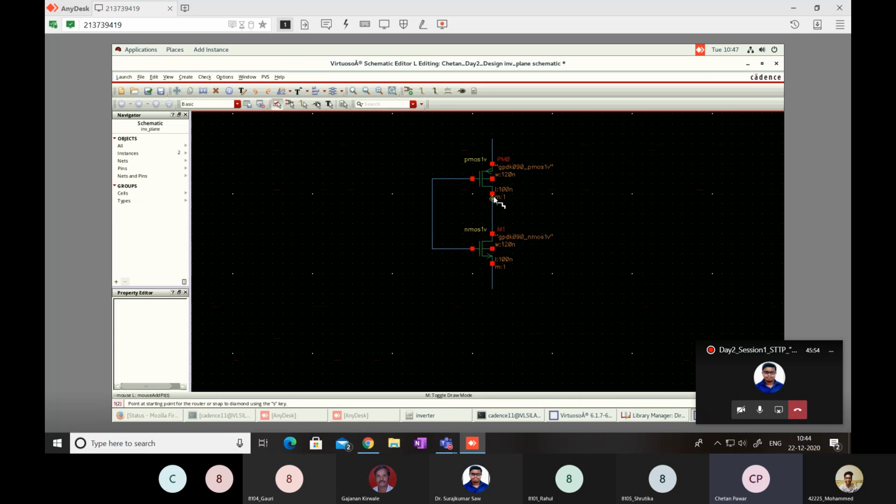Okay, Rahul, if you want to connect these two terminals, what you need to do? There is a shortcut for taking wire. That is W on keyboard. If you press W, one cursor will get attached to your mouse cursor. So like this way, one time you can click here, and then if you want to place the line floating, you need to click two times. Similarly, you can make the connection, like suppose if I delete this connection.